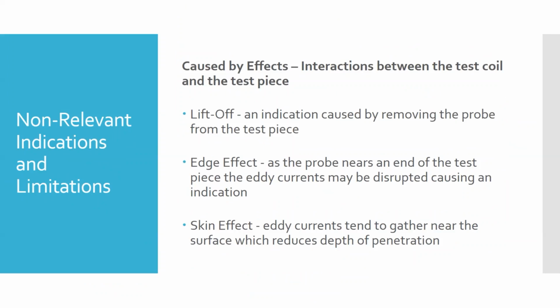Well, so what's the disadvantage to lowering the frequency? What does lowering the frequency do? It gives us greater depth of penetration, but there's a trade-off. What's the trade-off? The sensitivity goes down. So if you are setting your frequency in such a way that the depth of penetration is so deep that it's beyond where you would be looking for flaws, you're reducing the sensitivity in the area that you are interested in.